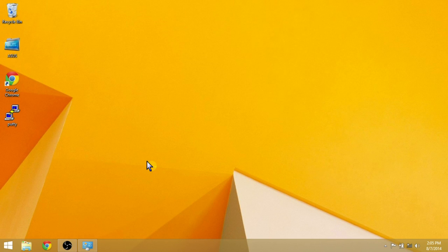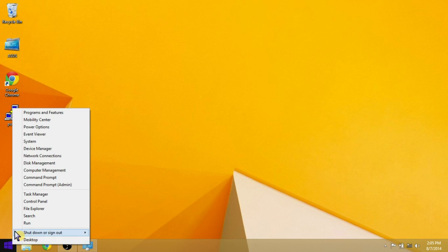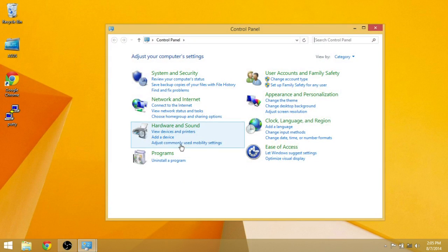Okay, I'm going to show you how to connect your Okapi Bluetooth and start logging data. First of all, we open the control panel. Make sure your Okapi Bluetooth is powered on and not paired with any device. If it is paired, delete the pairing on the device and power off the Okapi for a few seconds, then plug the power back in.